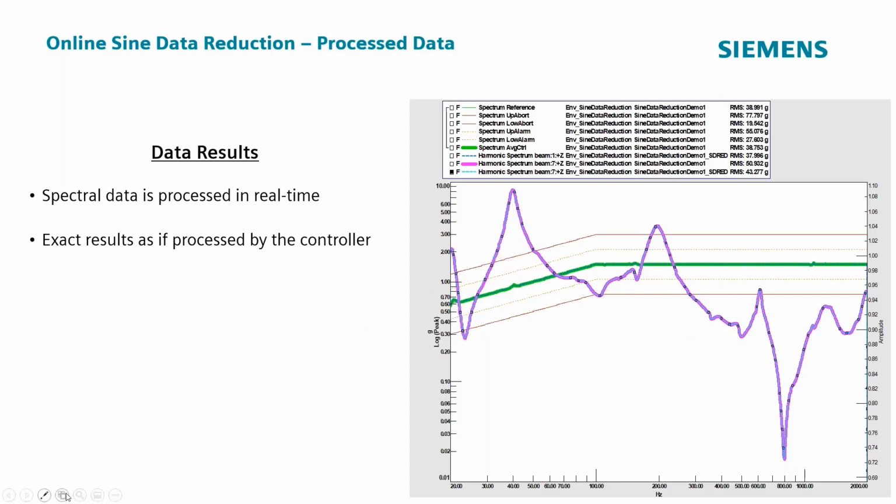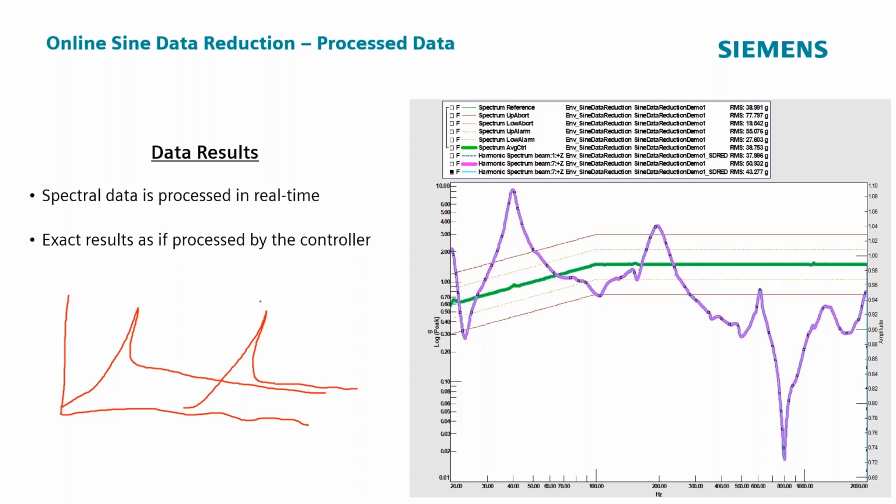Does that make sense? Yeah, I kind of like it. It's very focused, right? A single frequency at a time, huh? You get one single frequency, and you're taking a bunch of these FFTs, and if you try and average these together, you're going to reduce what this actual peak was because you're essentially averaging in some zero point here. So you're going to get a reduction in amplitude. That's what we don't want to do in sine. We want to know exactly what the amplitude was at exactly what the frequency is.